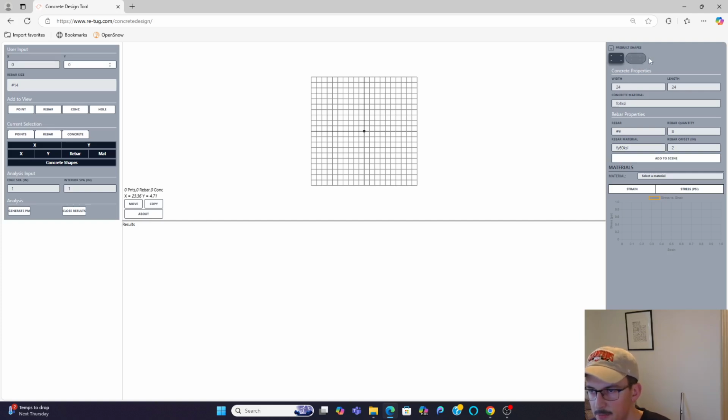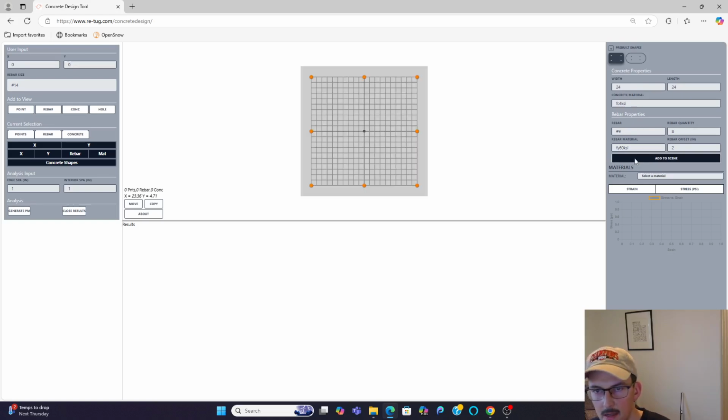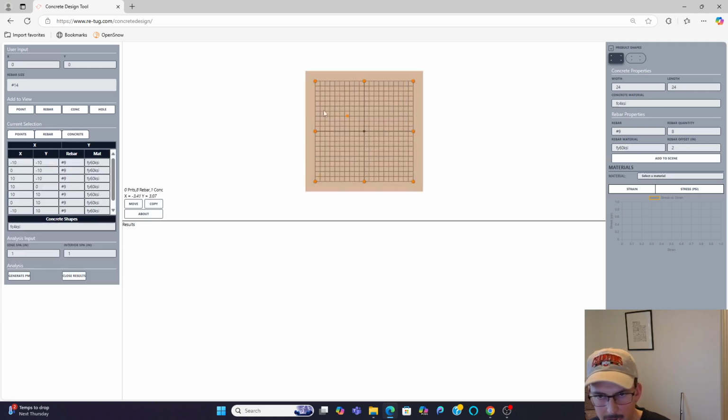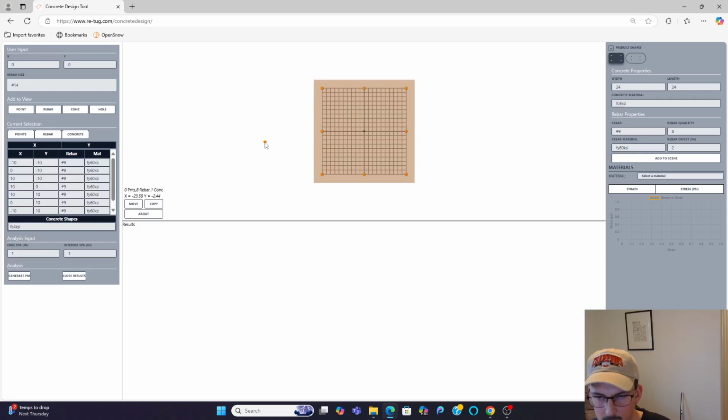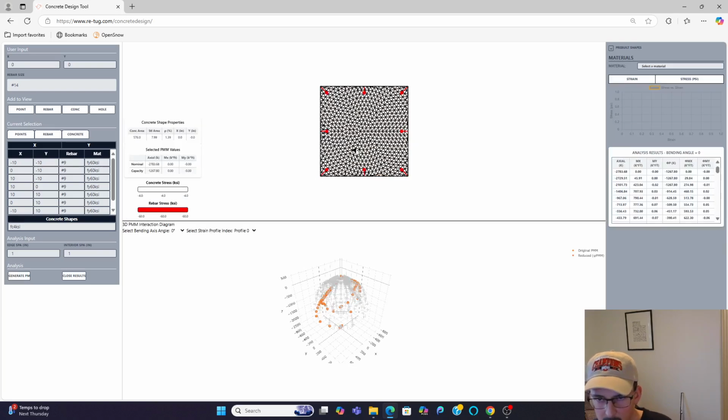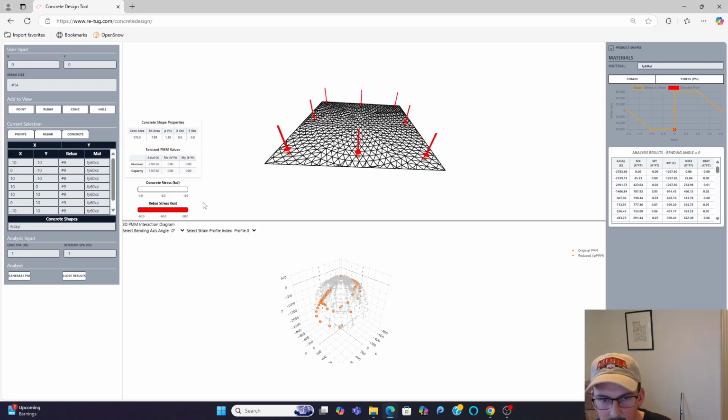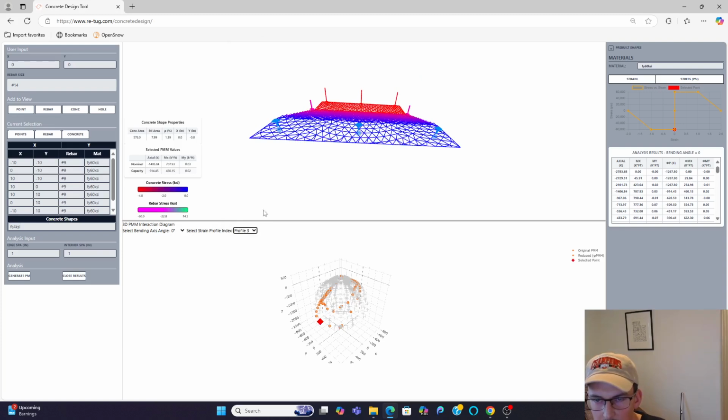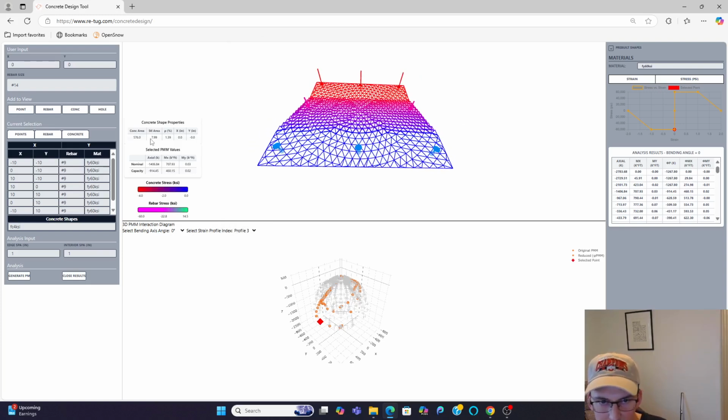When you do this, we have some pre-built shapes here. We'll do 24 by 24, a square, 8 number 9s. Pretty standard stuff here. Once you're happy with what you want to generate the PMM for, click on this button down here. It goes in and creates and calculates results. There is a clickable interface here where you can review the stress-strain state of any element in the scene, and it has some fun diagrams to help you see what's going on. You can see this is bending about the x-axis.